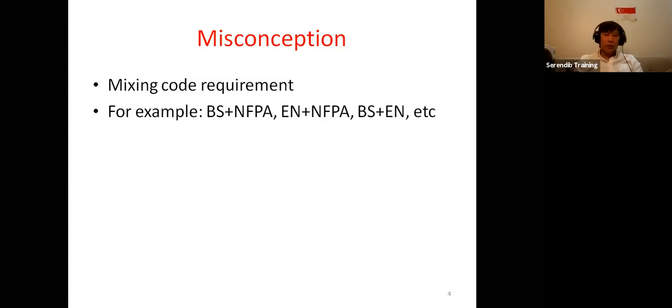So when you start to mix them, you are coming up with a hybrid cause and effect that will become very difficult to troubleshoot as you go deeper into construction, and even after handing over, during testing. Hopefully, cause and effect can be made correct at the point of handing over, so that when the facility management team takes over, they have a cause and effect in a particular building which makes sense, right?